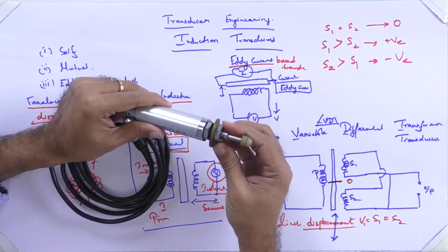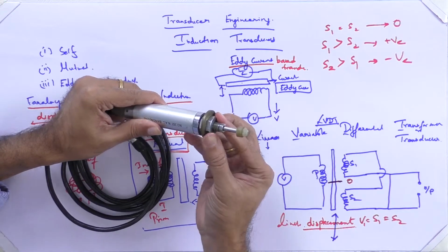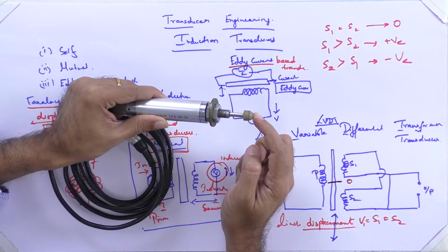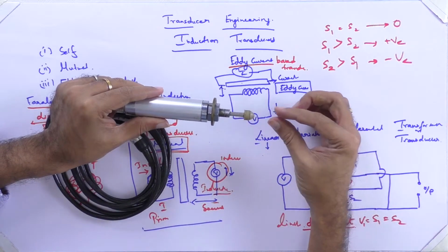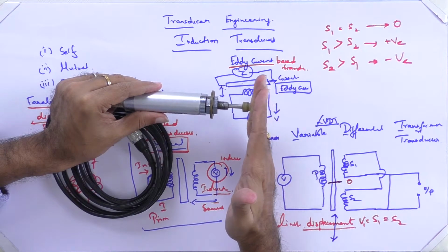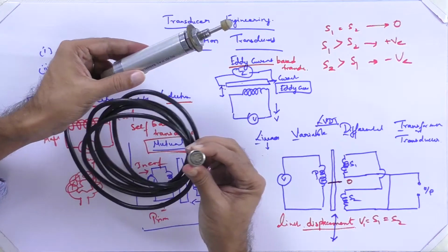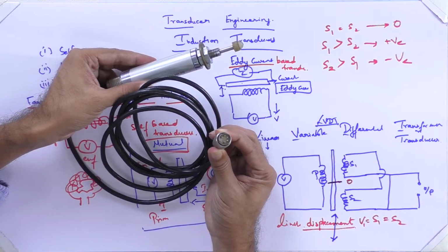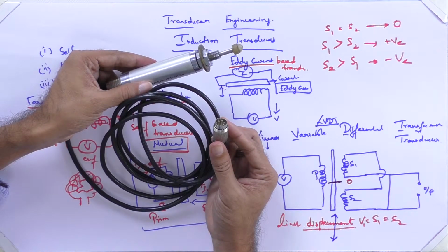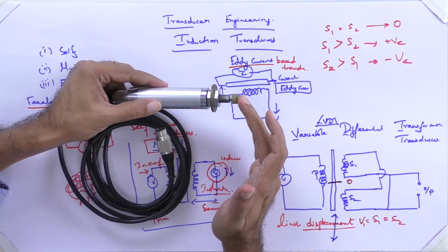So now you see again, the shaft can be used. Now we can connect anything here, any kind of displacement. When you want to measure how much I am moving my hand, we can easily connect this terminal to a computer or a microcontroller or anything, and then you can measure the displacement, how much it can measure.